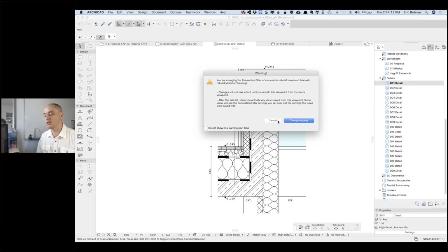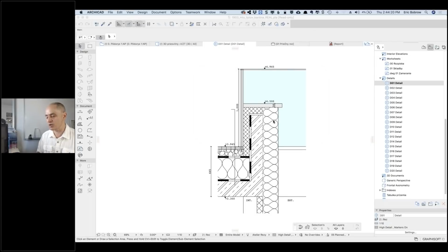So you can change the setting, but there's a real limit in terms of why are you changing the setting? Is it just because you think this is the wrong setting that it's got? What's your issue with it? The issue was that there were some elements made as new, and I couldn't see them in a detail. I can see them in 3D and in a section, but not in a detail. So I have to change these elements to existing, and then I could see them also in this detail. Do you understand? Okay. All right.